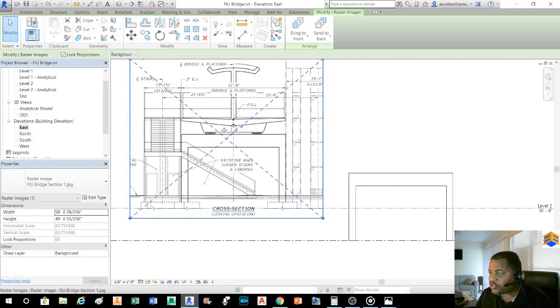So what I've got to do now is click the image, and then click where I want to drag the image reference point. I'm going to click right here in this corner, zoom out, and drag this down to this corner. Notice I already drew a line in here, but I got ahead of you earlier.